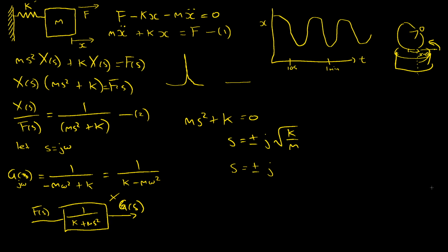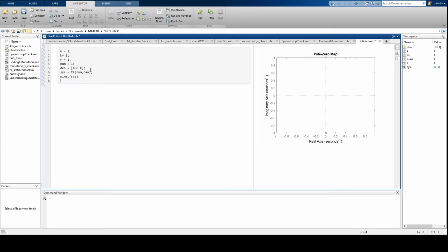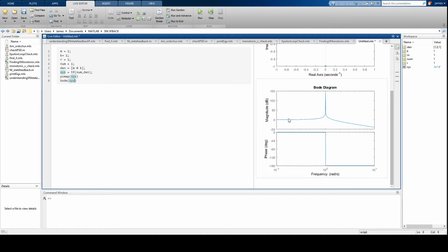So we'll swap back to MATLAB really quick. Now we're back in MATLAB, and we want to see what the frequency domain response is. In this case, I'm going to produce what we call a Bode plot of this system. And you can see it's now produced what we call a Bode diagram. Please ignore the phase component. We'll get to that later when we're dealing with complex systems. For now, we'll treat the magnitude. So here we have the magnitude of our transfer function in dB, like we were talking about, and the x-axis here is our frequency in radians per second because we're dealing with omega.